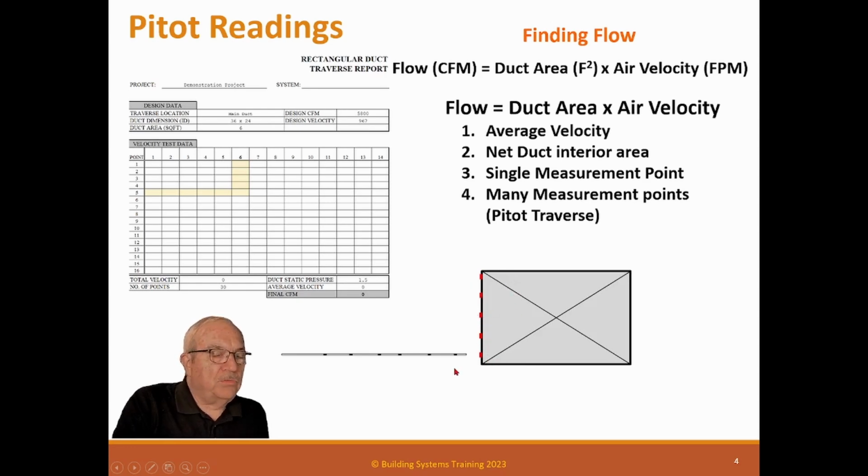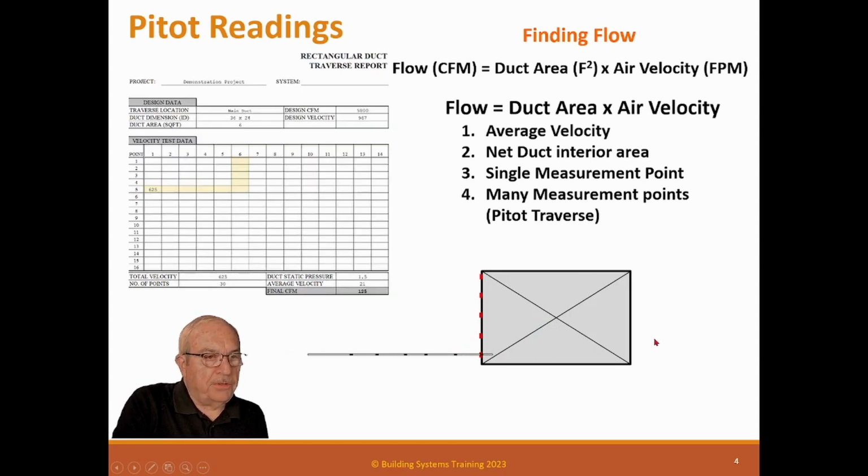And then what we do is we mark the pitot. This happens to be an airfoil. And we normally mark it either with a felt tip pen, or with a little piece of black tape. And you basically mark off the dimensions that you're going to read across this thing. You have this all hooked up to your meter back here, which I don't show. And then you begin to take your pitot and you read the first reading, the first black tape.